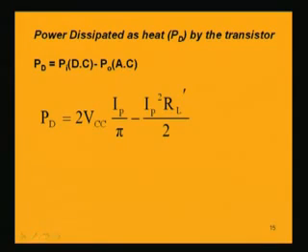So in this type of push-pull amplifier, the key point is that we are having class B operation, no doubt. That means a particular transistor is operating only in one half, but we are combining these two transistors to get the overall output current, and individually each of the transistors is operating in class B operation.